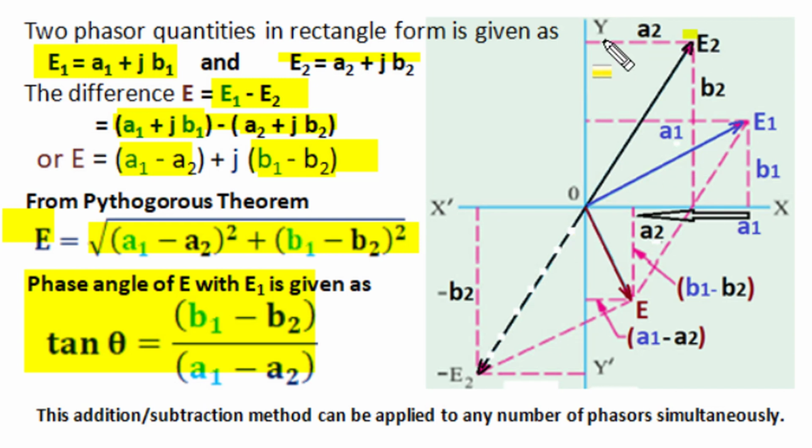And it is also illustrated here in this phasor diagram. This is E2, and when reverted becomes minus E2, and minus E2 is added to E1 to give the E1 minus E2 phasor. And now the real part of the resultant phasor is the difference of the real part of the first phasor and the real part of the second phasor. So A1 minus A2 is the real part of the resultant phasor. Similarly, the difference of the imaginary part B1 of the first phasor and B2 of the second phasor gives us the imaginary part of the resultant, and since B2 is greater than B1 in this case, the vertical part becomes negative. So our resultant phasor is inclined downward from the horizontal line, so its angle comes out negative.